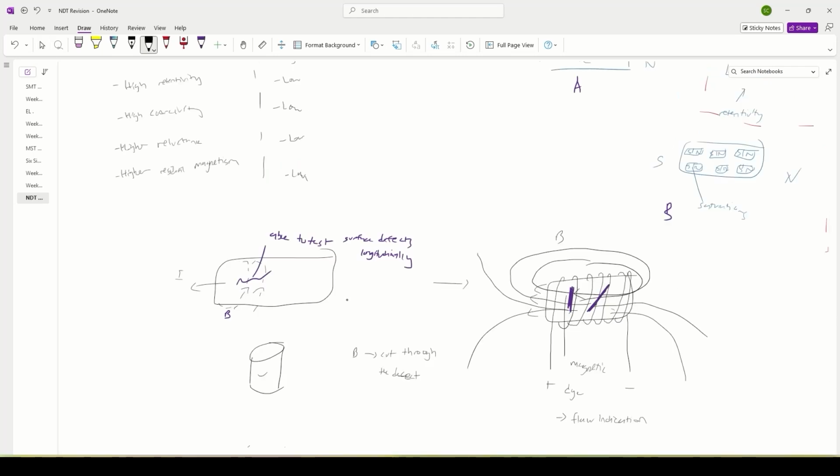The angle also affects this. Make sure that the angle is less than 45 degrees for the circular rotating magnetic field. If it's more than 45 though, we have to use a straight line magnetic field to be able to cut through the material. Only when the B field cuts through the material can it interact with the material easier.